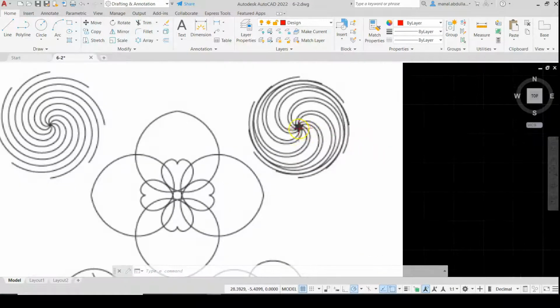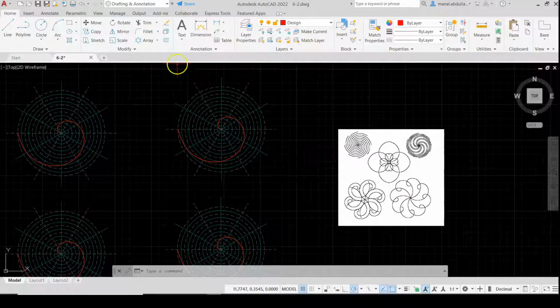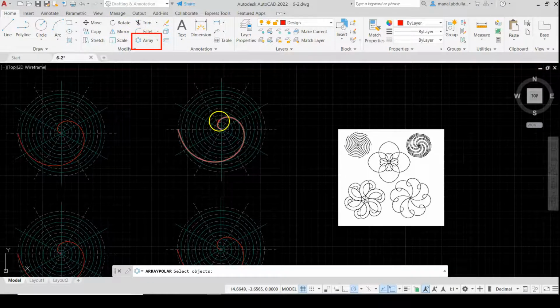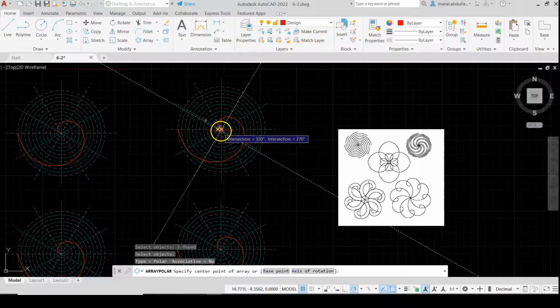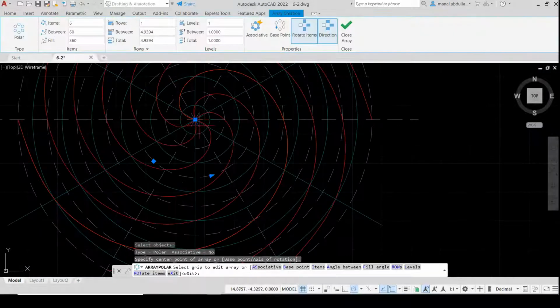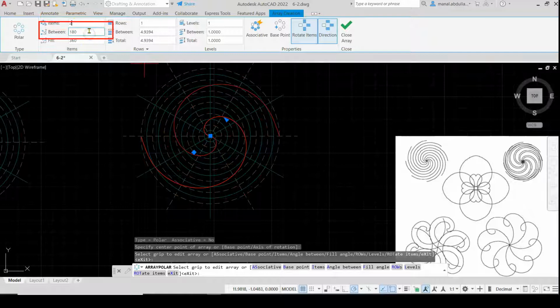First thing you notice is that we do have 2 close together, then we have the polar array. So in this case, I'm gonna make the polar array, enter, and let's pick the middle like we did, but this time we just need 2 items, and we need to modify the distance between.